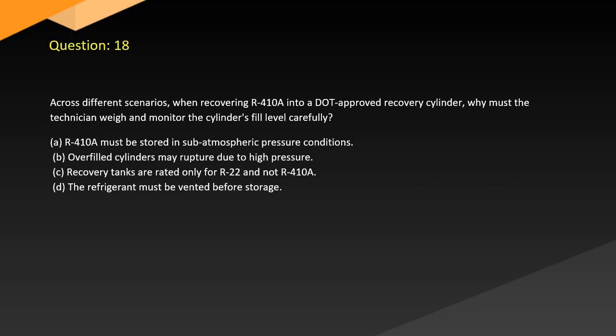Question 18. Across different scenarios when recovering R-410A into a DOT-approved recovery cylinder, why must the technician weigh and monitor the cylinder's fill level carefully? A. R-410A must be stored in subatmospheric pressure conditions. B. Overfilled cylinders may rupture due to high pressure. C. Recovery tanks are rated only for R22 and not R-410A. D. The refrigerant must be vented before storage.